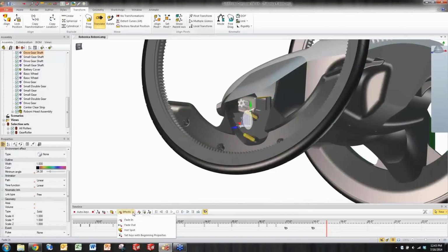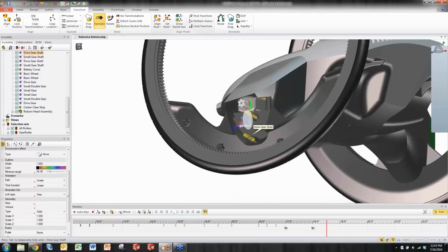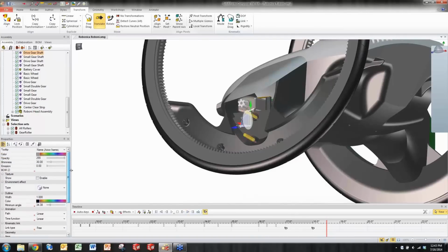We can control color of components. So without these selected, you'll notice that they're gray, like a dark gray, just like a lot of the components in my model. I'm going to change the color. So first thing I want to do here in the properties window, I'm going to come up to the color of the component. I'm going to highlight that property because this is the property I'm going to be recording. So from here, I'll set a property key, move my time bar forward a small increment. I'm going to have this flash a green color. So I'm going to choose this.